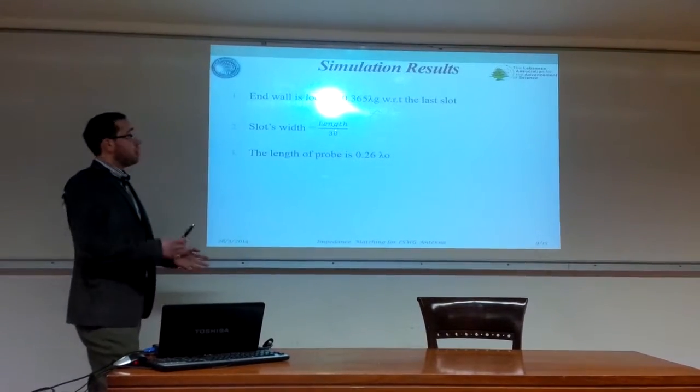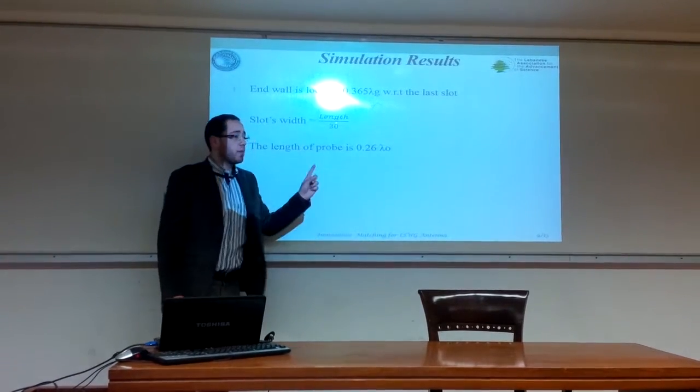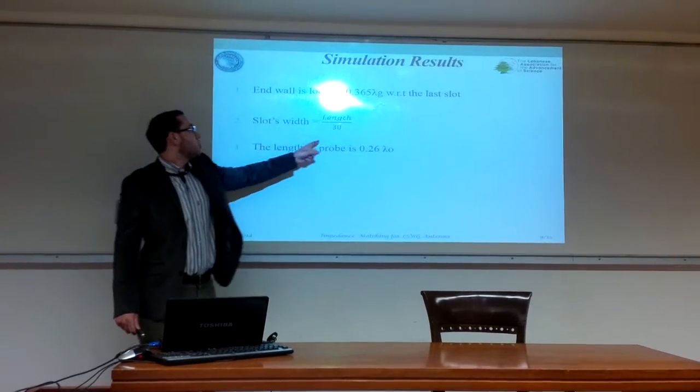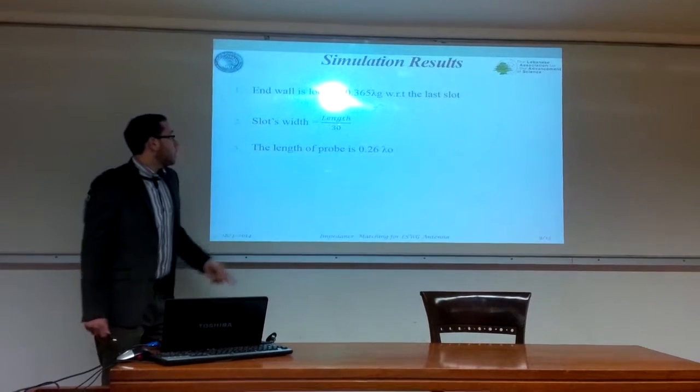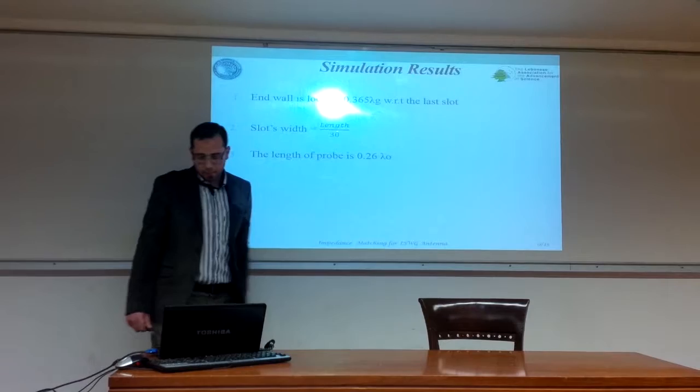Okay, here we have the summary of all the optimizations. The end gap was found to be 0.365 lambda G, the slot we chose to have a length over 30, and the length of the probe was 0.26 lambda 0 instead of 0.25.